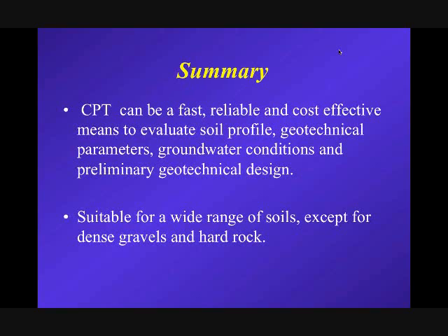In dense gravels and hard rock, you're going to hit refusal. You're not going to be able to push in those types of soils. Fortunately, humans tend to live in cities that are close to rivers, coastal areas or lakes, and so the soils tend to be relatively soft where a lot of people live. So the CPT has pretty wide application in many parts of the world.